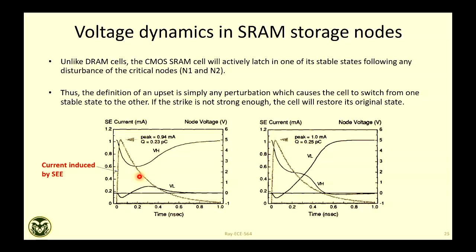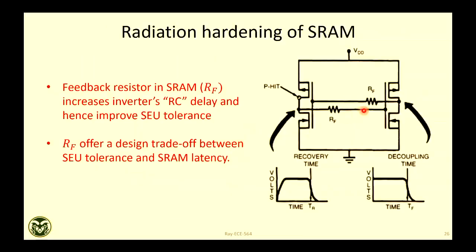You can play with those resistances of wires, and in one aspect, you can just make those wires more resistive, which is bad for typical or usual operation, but for space application, maybe we can compromise with some delay. You can intentionally make some of those SRAM cells more delayed, and that can cause radiation hardening of the bits.